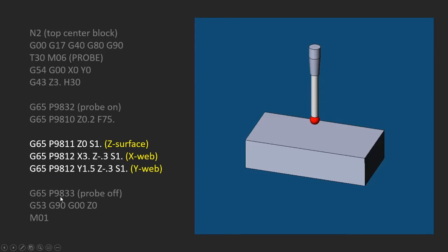But I put it in here so we can have it ready for this one, because in this case, if I didn't turn it off, it would just go ahead and put the probe away, calling up the next tool or whatever. And meanwhile, the probe is in the tool changer, flashing away that it's still on. So this is an important part of this one now, that we turn it off, because these cycles do not shut it off.